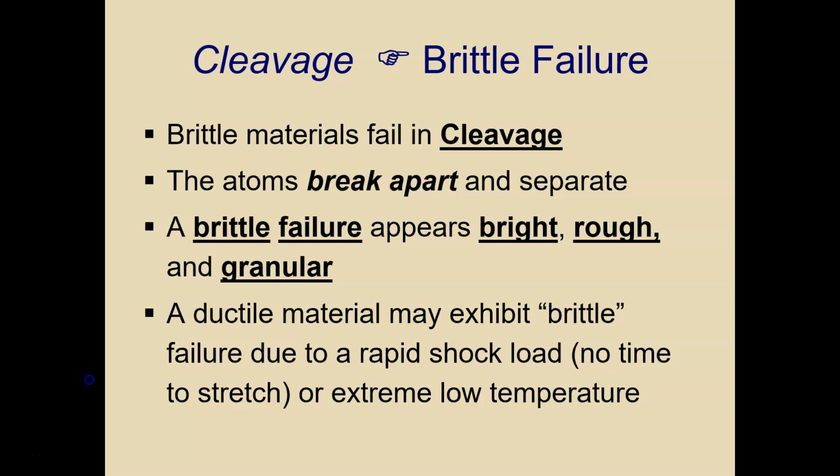Its main characteristics are that it is associated with a particular crystallographic plane. It is increased by lower temperatures and higher strain rates. More commonly in metals, the fracture surface contains varying fractions of transgranular cleavage and evidence of plastic deformation by slip. Cleavage fracture surfaces appear in steel due to sudden or impact loading, low temperature, high levels of constraint, ambient temperature, or heavily cold worked parts.